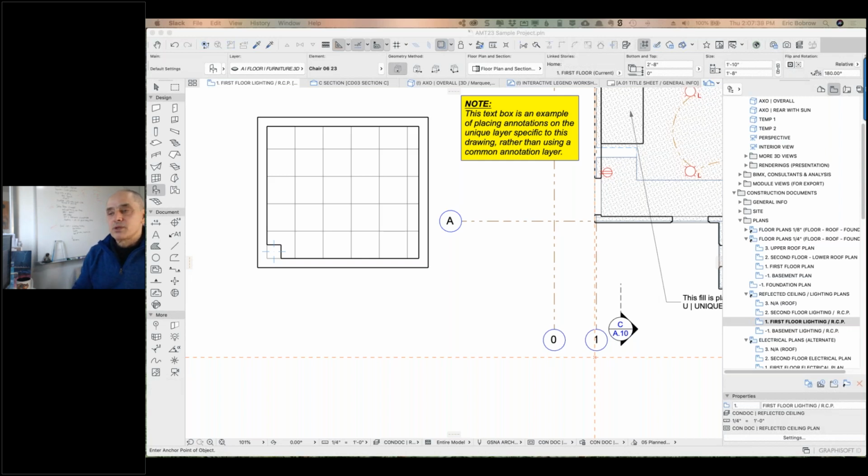Let me just tell you conceptually that you can draw just a roof. So a roof can be used for a ramp. Now, roof has a limitation that if you're doing a curved ramp, it's not going to work so well because it'll go up just on one plane. You can use the stair tool, and I believe there's even a favorite in at least the US library for a ramp.